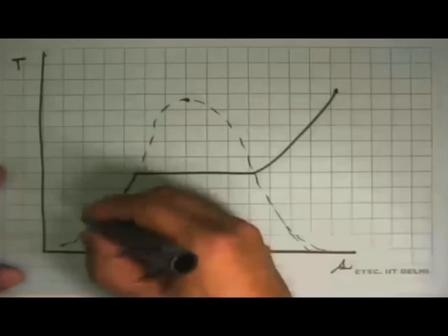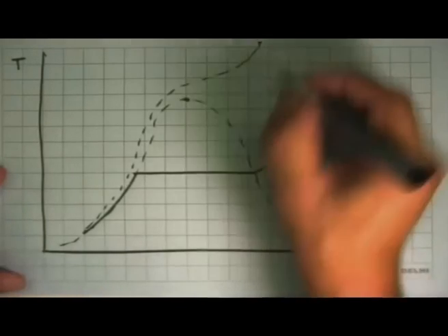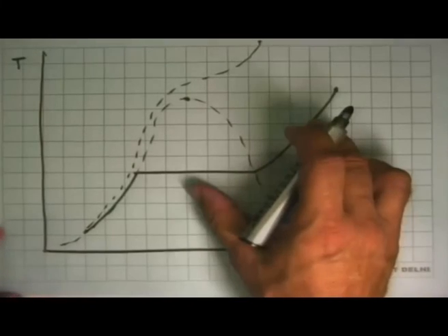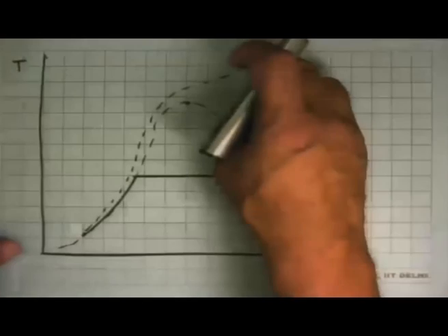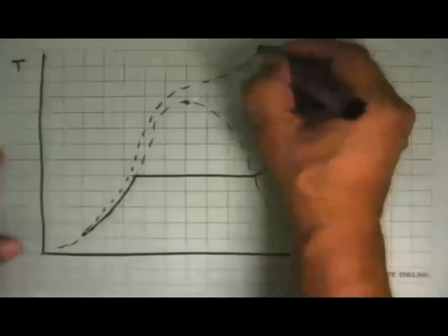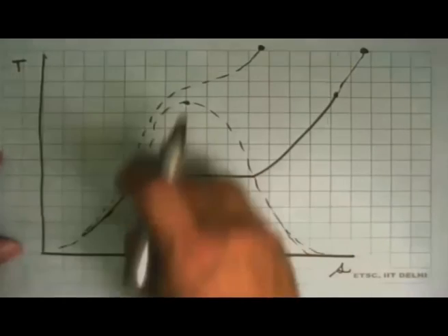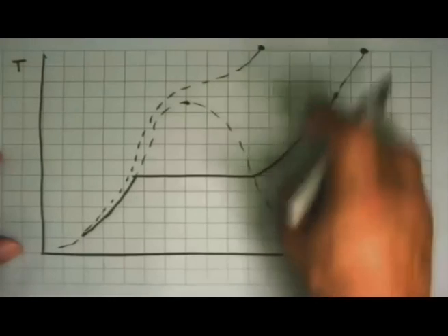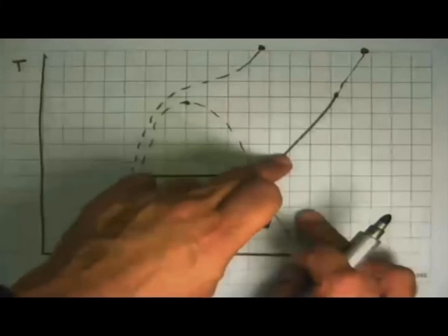But if you have a supercritical boiler, this will go off like that. Which means I don't need to design 3 different things, only one thing. And the reason why we design it is that when you use steam at this condition versus a steam at this condition, the thermodynamic efficiency of this or cycle built around this is going to be much more than the thermodynamic efficiency of this cycle.